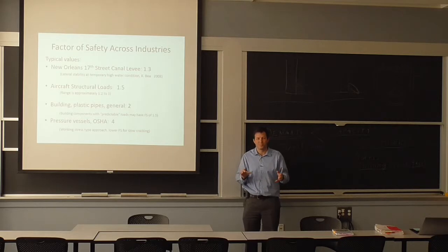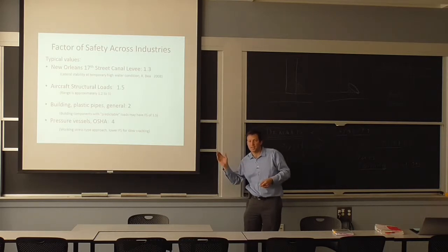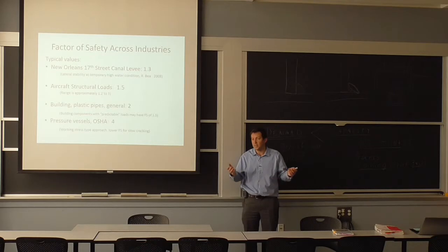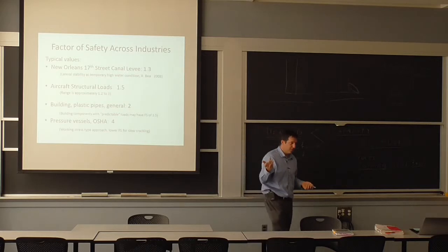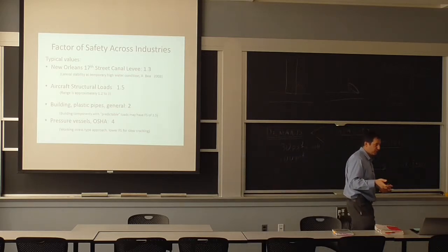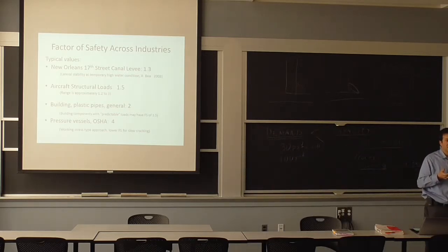Is that great? Well, I can't say it's the best way, because now if a hurricane comes in, and it's not just hydrostatic head, it's cyclic load and all that, they didn't take that into account, guess what? We had a problem, right? That happened in New Orleans. The levees they thought had a safety factor of 1.3 did not, because of the exact conditions and how the loads were applied.